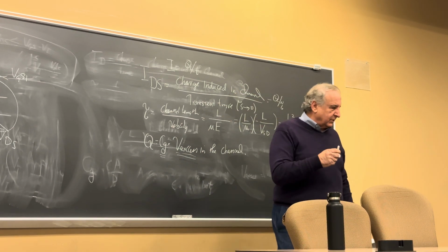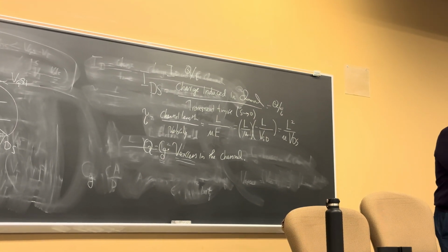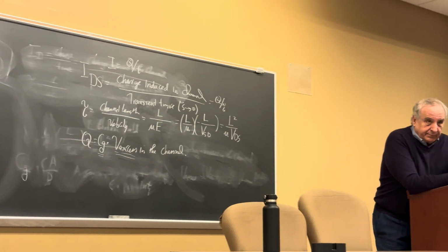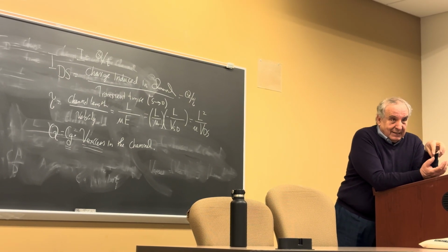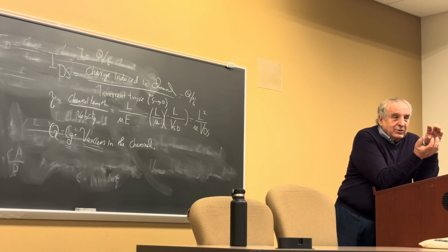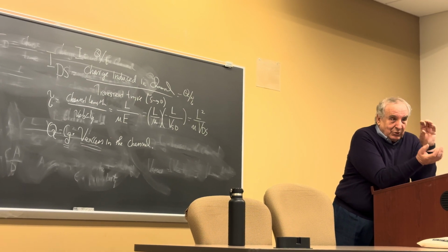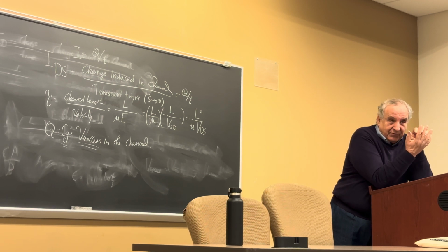What is the excess voltage? We apply VGS. Then we reach threshold. Because threshold opposes VGS, the remnant is VGS minus VT. That's the excess voltage, the difference between the two voltages.